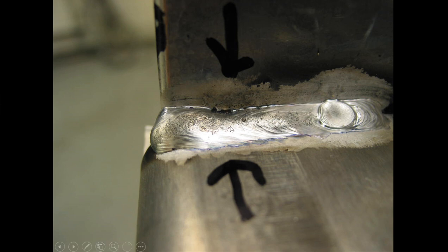Here's a chunk of oxide. It's an interesting picture, and I'm just going to share something with you. This is a weld that started here and went back and created what I consider to be a perfect termination. It utilized the heat from the area that we just welded, and the current was actually ramping down while the crater fill was being done. You rarely see one that good.